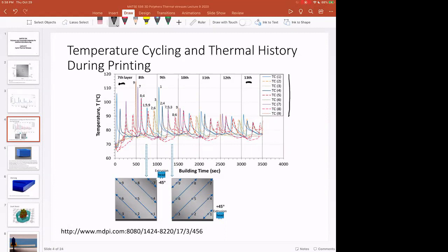So this now gets really at the heart of the matter of really complicated cyclic thermal stresses in parts, and learning how to model this, or being able to model a whole part layup like this, is really difficult because you need to know all about the heat transfer, the heat conduction, coefficient of thermal expansions, all those sorts of things. And so we still don't have a comprehensive thermal model for a lot of this printing technology, although I'll show you an example of one in the future when we talk a little bit about control software and how people are trying to control these printers.